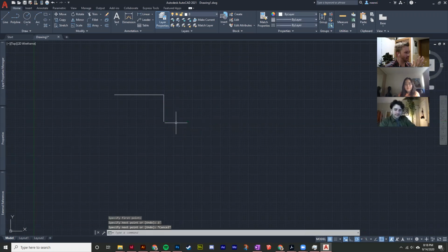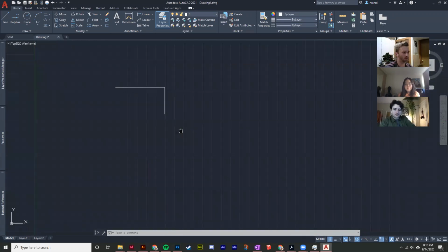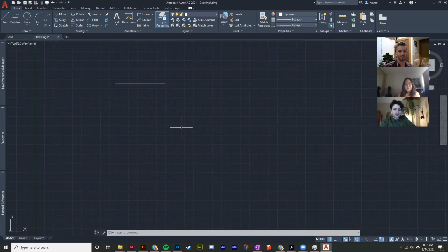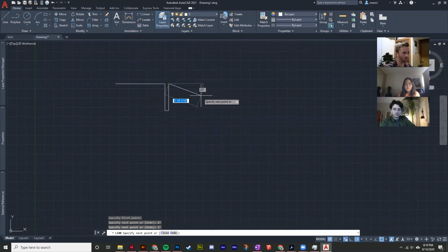Another thing to remember is that walls have thickness. I noticed in a lot of your experiential maps, the wall is just a line like I've drawn now, but it's important to remember that that wall has a material, it has a structure inside, and then it has a finish over it. So most walls are either timber or metal framed. So they have that inner structure, and then there's drywall on top of it, and that's what makes the wall surface that we're used to. Typically, that's about 4 to 6 inches. I'll do 5 just to be safe. So my wall thickness is 5, and I'll go back up to 3.